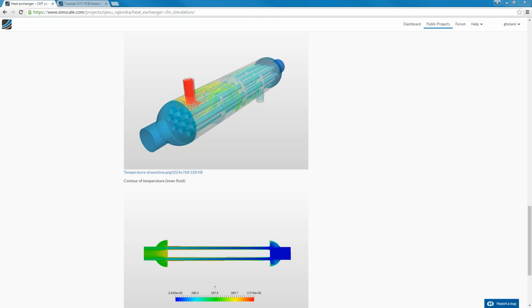There's a question, can a transient heat flux be included in the CHT boundaries? If I'm understanding this correctly, you're asking whether we can define a value that changes over time or in the course of the simulation. That is in principle possible, but it falls under the same input way as we have with CSV files and with functions. To be honest, I'm not sure if it's already available for heat flux or if we should add it. But based on this answer, I would say if it's not there, it's very easy to add. I suggest to get in touch with our support, and they could give you more information.